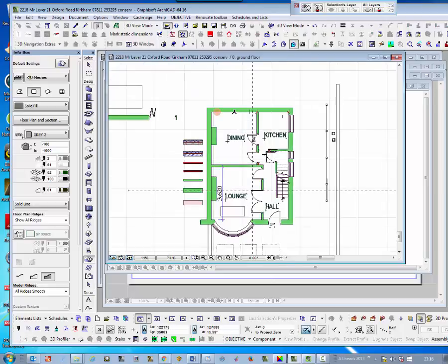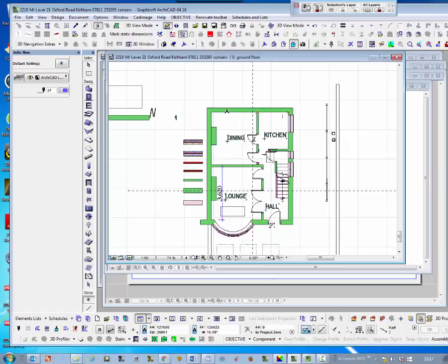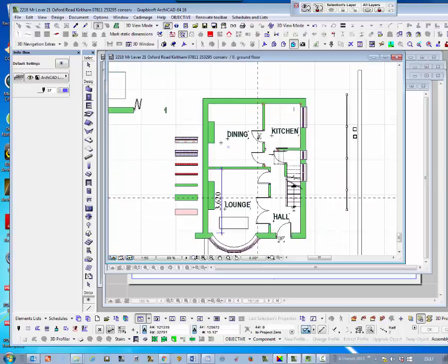Holding against the edge of that wall with the mouse, you see the Mercedes cursor. First I would go down here and select the hotspot, and then go into the top there, Mercedes cursor against there, and I'm going to press the Y key. I'm going to put in the figure of 2450, and I'm going to press minus because it's going down the drawing, and then I'm going to press the mouse button, and that has put my hotspot at 2450 down there.